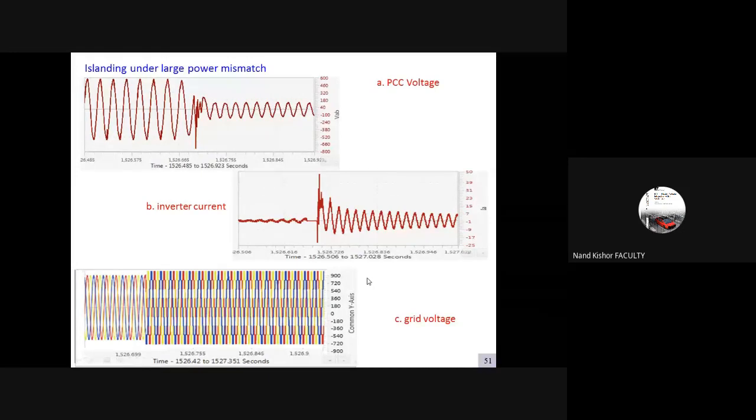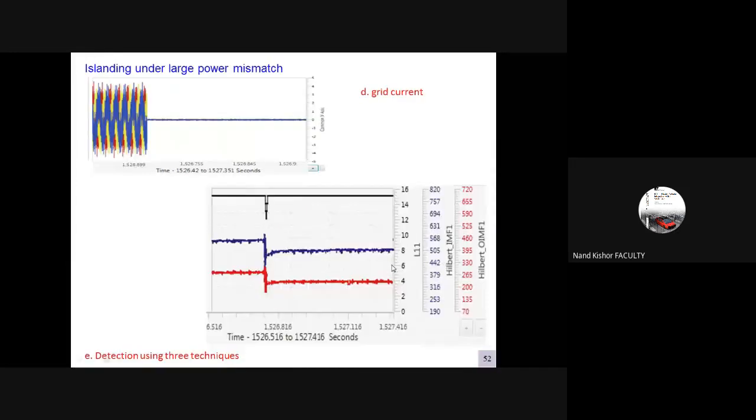With this condition, we have the islanding here, right? So we want to detect the instant. As you can see, the grid current side, because the switch is completely open here, right? This is on the DG side, the PV side. With the wavelet and the EMD techniques, we are able to detect the instant of the islanding event in real time, with the different techniques here.